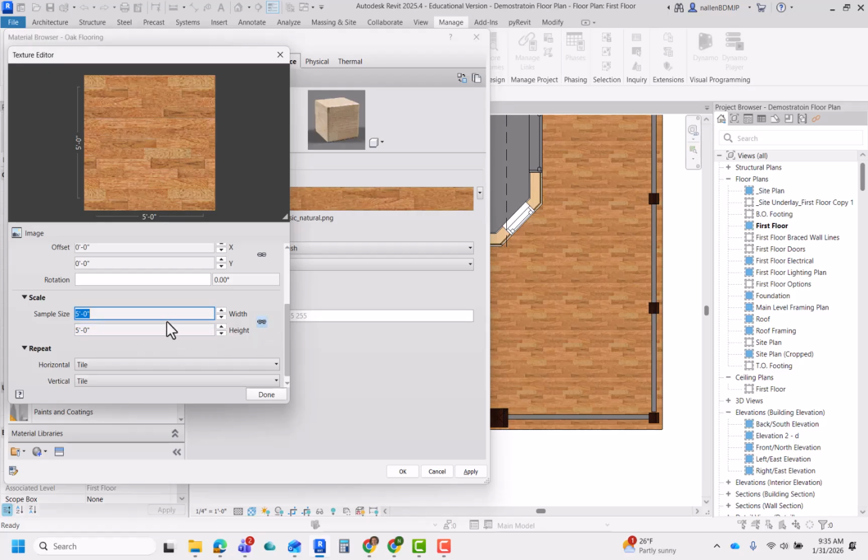So if that's the case, let's go back to like 2'6" here. You can see that it's not working as I do 2'6". For some reason in this area of Revit, you have to put in the foot symbol, and it still didn't work. 2'6". Let's try that. There. Okay, so I've got my 2'6", and I'm gonna unlock the proportions so that in the width I can